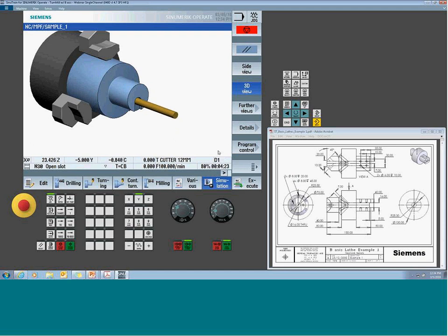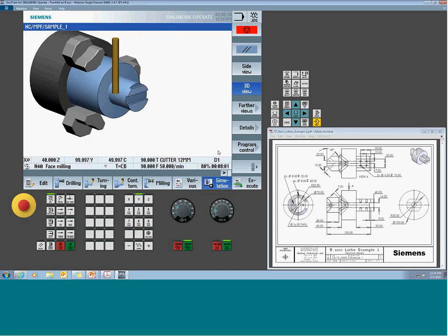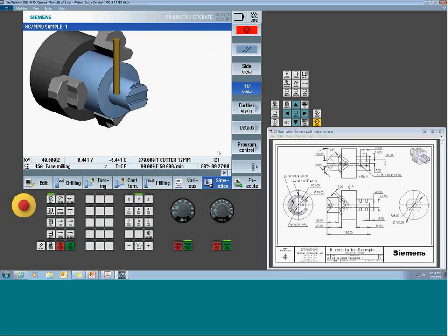So we'll let it simulate the whole thing, just to give you a refresher of all the ops. First, the peripheral face, it's actually a face Y, or peripheral milling, but we want to use an X and Y motion. And we face off the next segment.